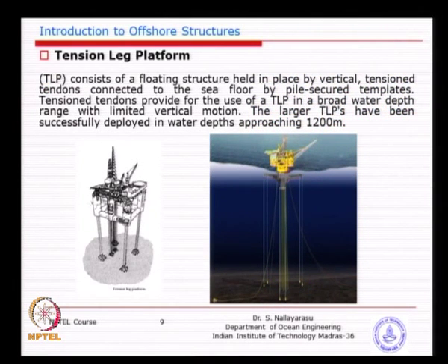We have seen this earlier, tension leg platform. The concept is very simple, very similar to a simple floating pontoon. The load or the payload is at the top and it is floating because you have excess buoyancy. So, you may see that there is a horizontal pontoon. The pontoon is connected to 4 legs, and each of the columns is connected to the ground by means of tethers.